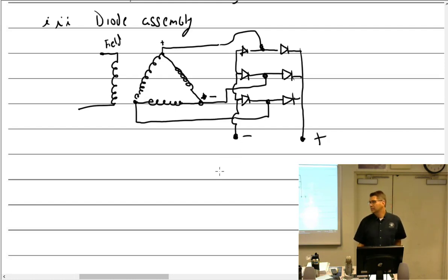Why? Diodes. So current tries to roll backwards, just hits a diode, it's done. It's got six big diodes in there for winding like that. So the diodes rectify and act as a reverse current cutout.